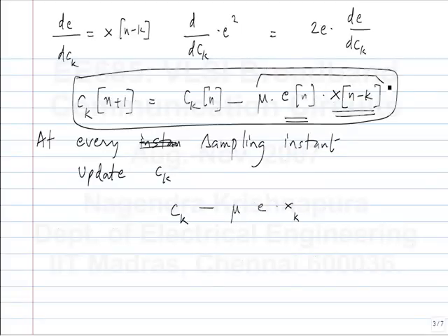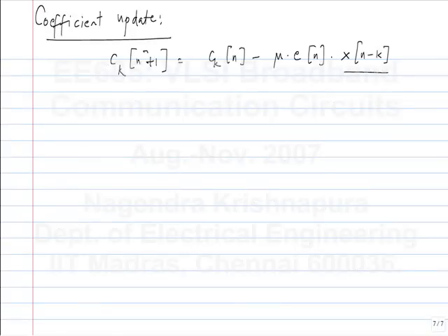Or when I was discussing receive equalizers, I said one way was that we sample the signal and convert it to digital. In that case, we multiply in the digital domain. So, x of n minus k is the quantity that is multiplying Ck to get the output y. So, you need to generate the product. Mu is fine, it's just a scaling factor.